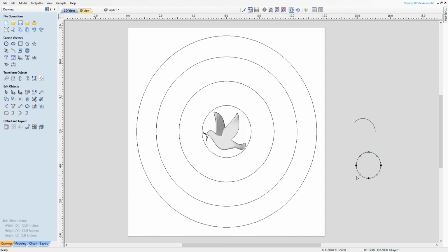And what I did is, I'll do it in 2 steps so you'll understand it. I cut the vector, I went to 3 o'clock, and I cut that vector, and then this part here I deleted. I went back up here and I did the node edit again, and I chose this right here and I cut this vector. Go back to the keyboard, press N to get out of node editing. I chose the red part to delete, and that was my cross rail.